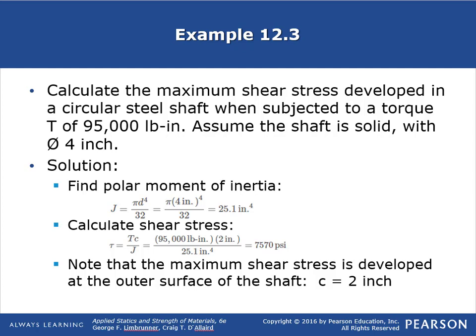Next, we're going to calculate what the shear stress is, and note that the maximum shear stress is developed at the outer surface of the shaft. Therefore, the c that we're going to substitute in this equation is 2 inches.